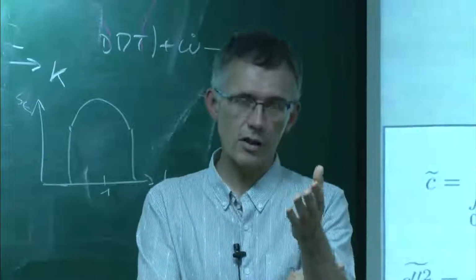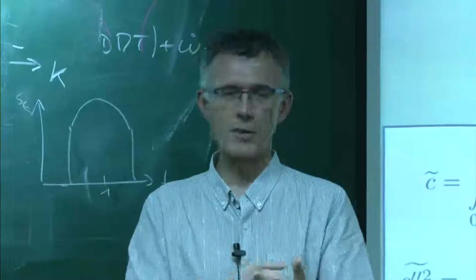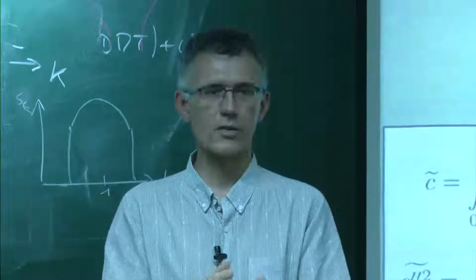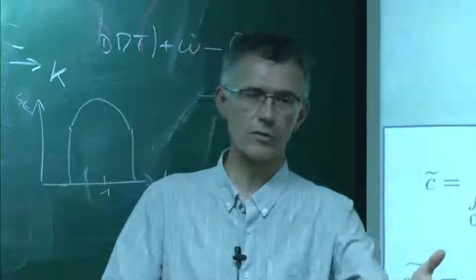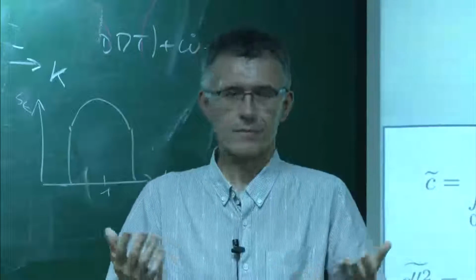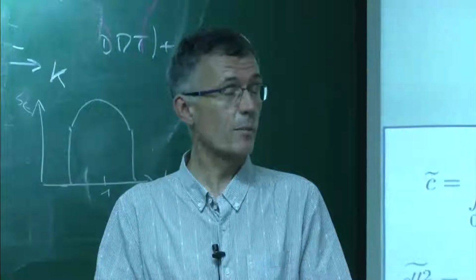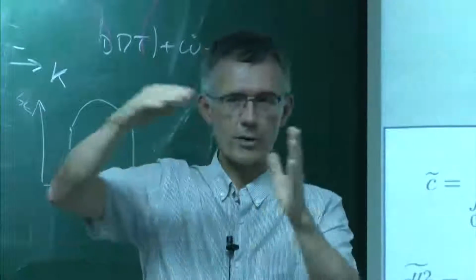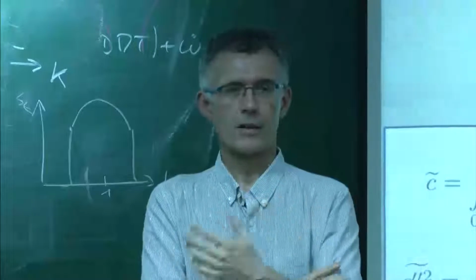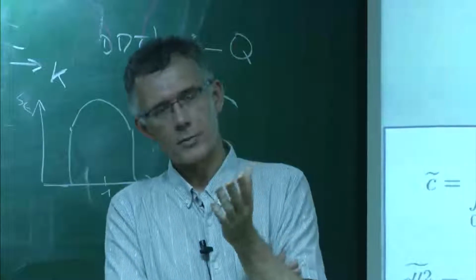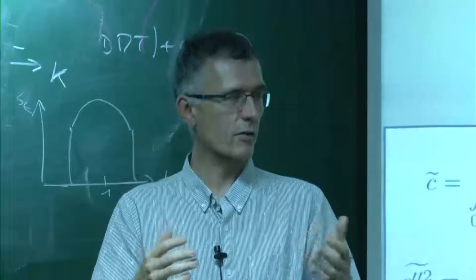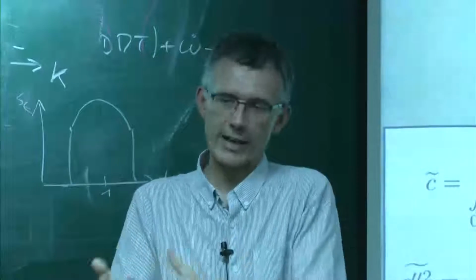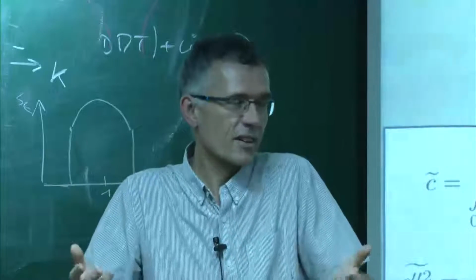If you start changing the constants, some people do that. Some people have libraries of constants. So they have one constant at 1 bar, one constant at 10 bar, one constant for lean, one constant for rich. Yeah, it's been published actually. I have a paper for eddy breakup where the guy published a table of constants in a matrix. You can pick up your constant. It may not be that stupid if you're not interested in the scientific aspect of the problem and just want a tool to be able to reproduce certain things. Why not? But from an academic point of view, it's not interesting. I don't want to do that.